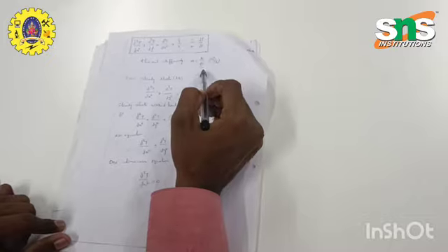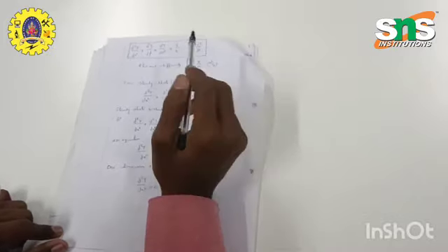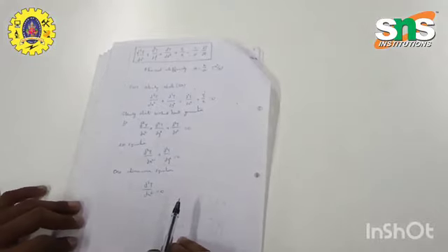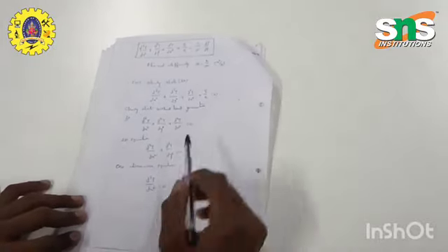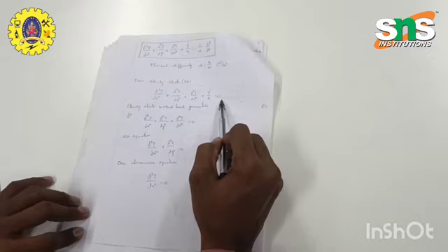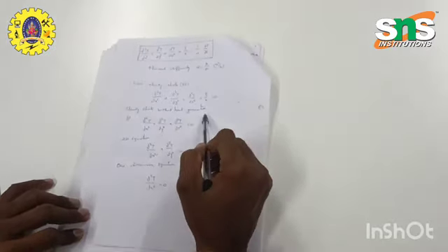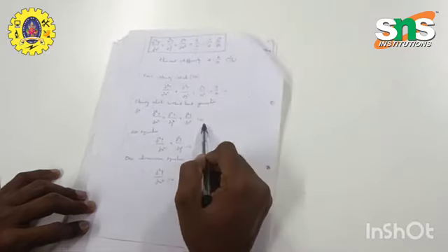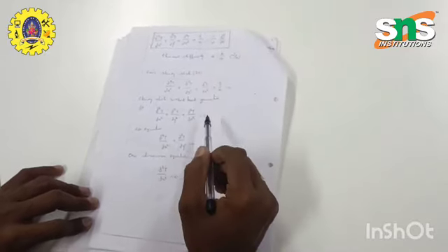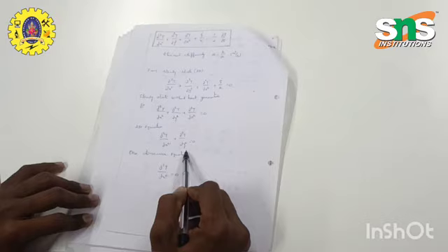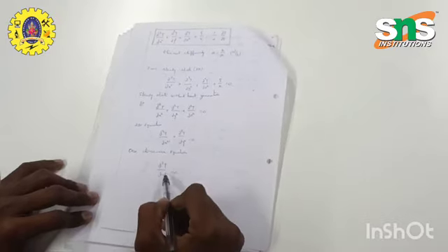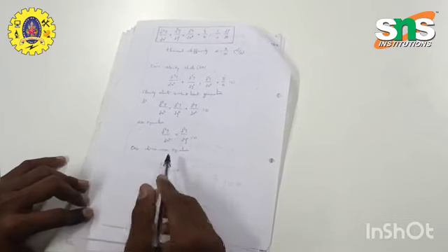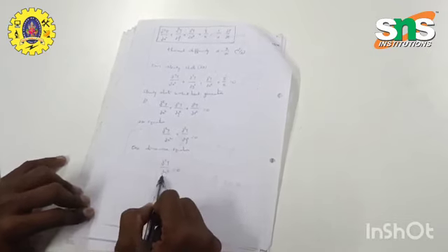Alpha has the unit meter squared per second. For the final equation we consider assumptions for different cases. For steady state, the right-hand term will be zero, and for steady state without heat generation, the q dot by k term will be neglected. For the 2D equation we consider the x and y directions, and for the one-dimensional equation we consider a single direction. So this is the general heat conduction equation in Cartesian coordinates.